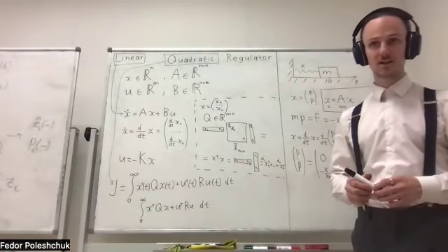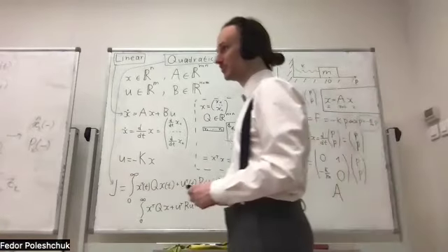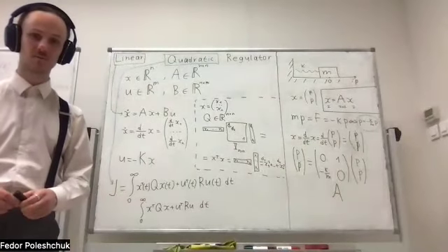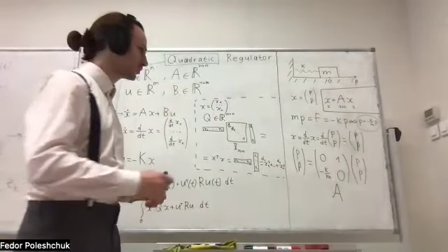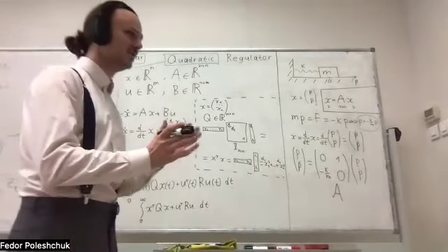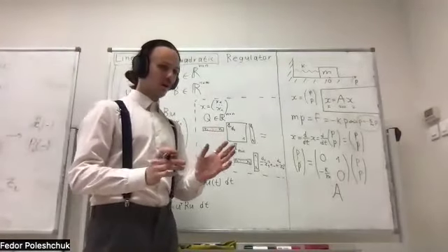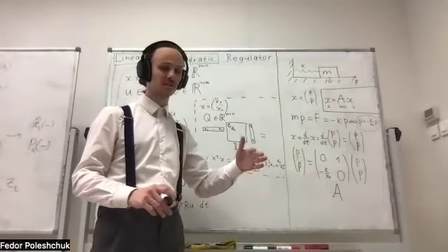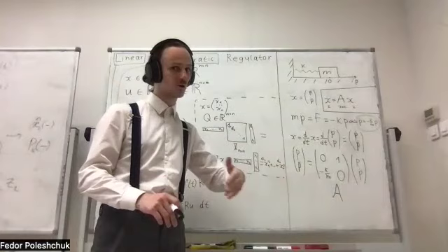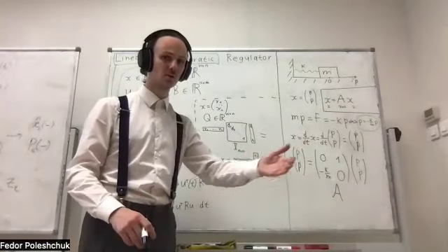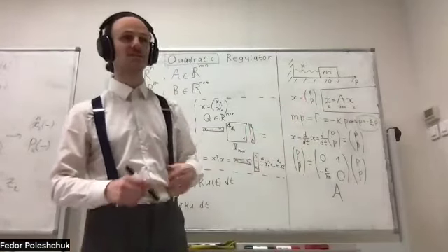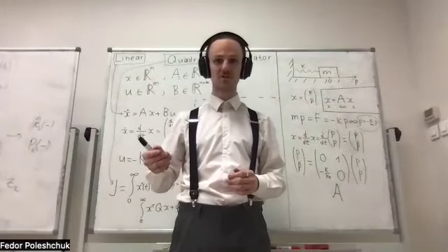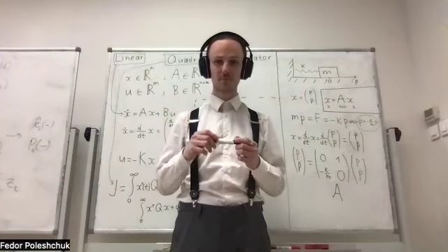And quadratic forms are good because we can minimize them by differentiating. And also, if we want to minimize the deviation from a certain desired trajectory, a quadratic cost or quadratic loss, a function that grows quadratically, is good for us, because the further we deviate from the optimal trajectory, the higher the cost goes.